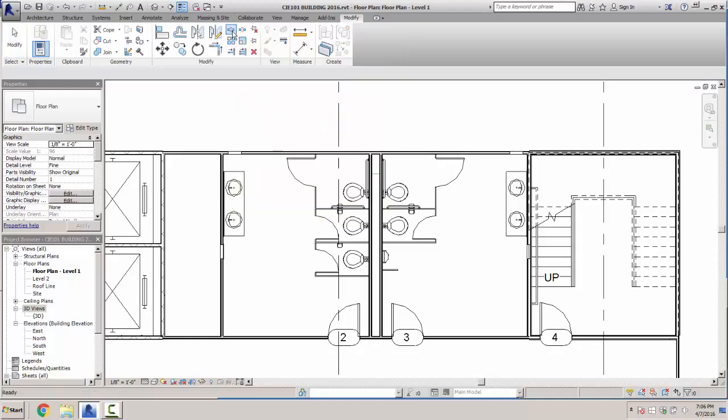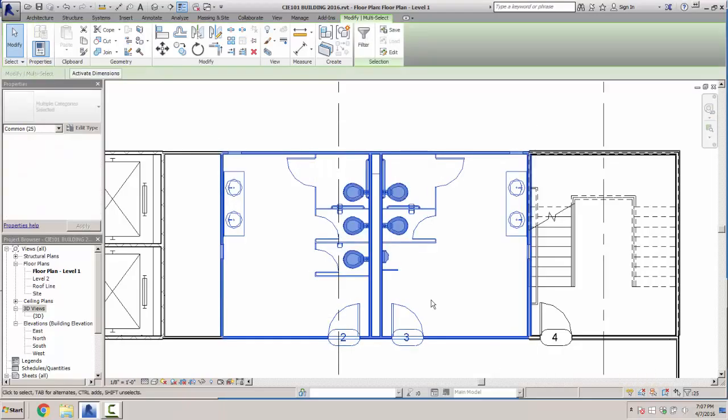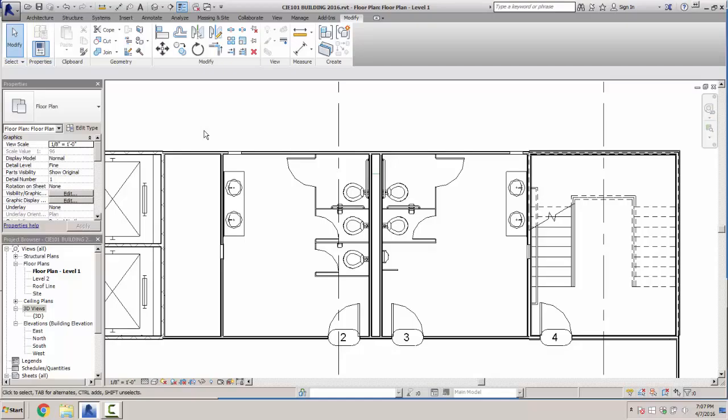So we're going to split our wall. We'll split it here. Should already be split there and there. We'll split this one here. And then we'll hit escape twice. Now we'll select it all. But I don't want the stairwell. Should probably not be.